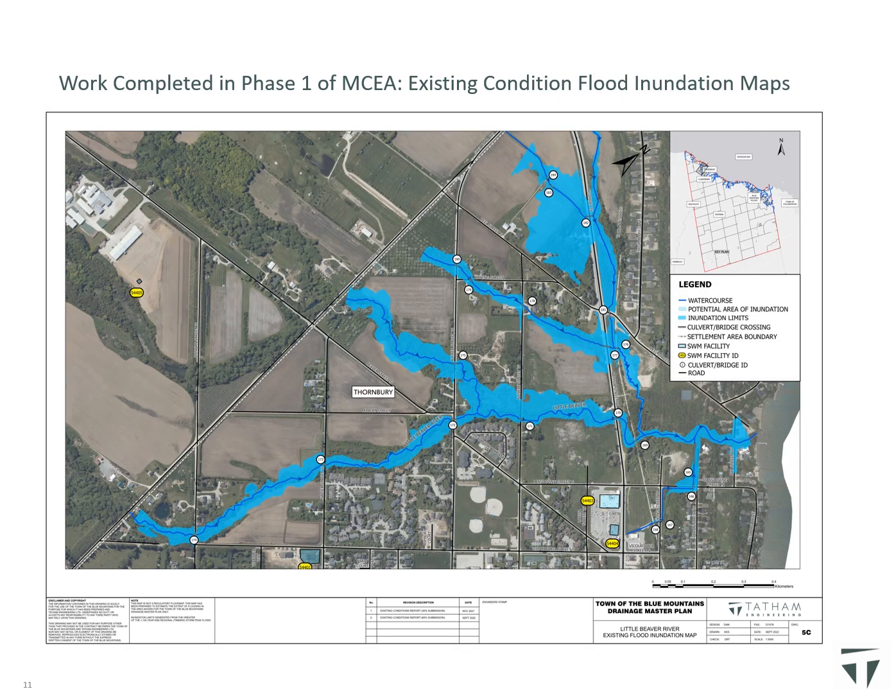The existing conditions major drainage system models were also used to create flood inundation maps for the 38 watercourses modeled across the town. These maps show the maximum modeled flood extents resulting from the greater of the 1 in 100 year return frequency design storm and the regional storm. The flood extents were determined to provide an up-to-date limit of flooding through the study area to identify impacted properties and assess the impacts the alternative solutions have on flooding.